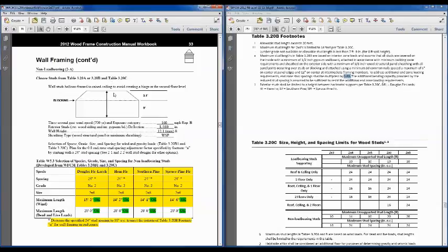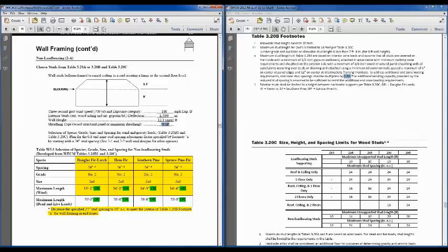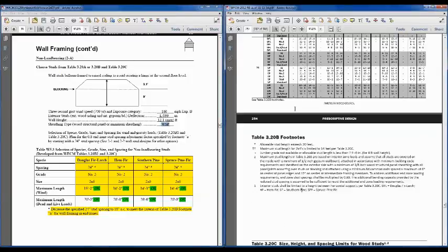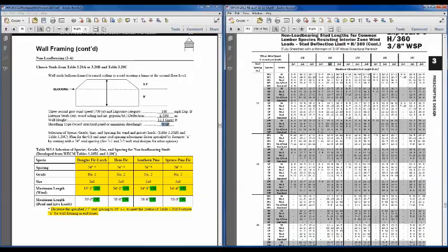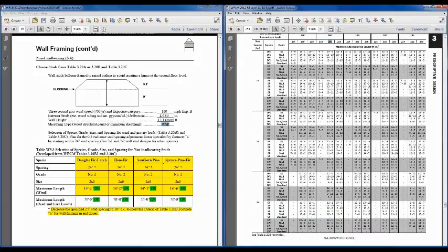We've designed 6-foot studs there. So we're going to design these 9-foot plus 3-foot studs here. So we've got 12-foot studs that come up to that vaulted ceiling location. So then we're going to design a 12-foot stud, and again, we've got wood structural panels on the outside. And again, going back to our table here in the wood frame construction manual for 160 mile per hour wind loads, we know we're going to be looking at 2x6s, and we're going to drop down here and see if 24 inches on center actually works.